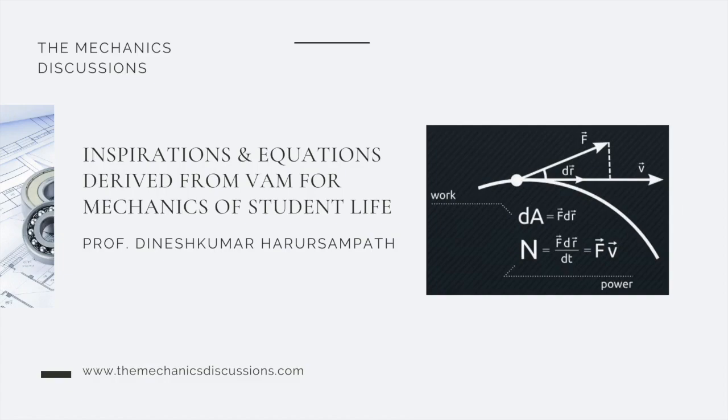See, most people are always wondering why the Lagrangian is defined as kinetic energy minus potential energy. Always we've been talking about conservation of energy, which means the total energy is the potential energy plus the kinetic energy. Why shouldn't that be maximized or minimized? No, this is the difference, because that is what you're able to utilize. There is a latent quantity which is the potential energy. How much of it you are extracting into kinetic energy is what this difference is all about, and that's what comes into play in life, and in a mechanical system, in an aircraft: how fast it flies, how much further it can fly, the range.